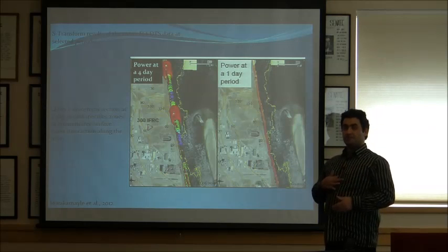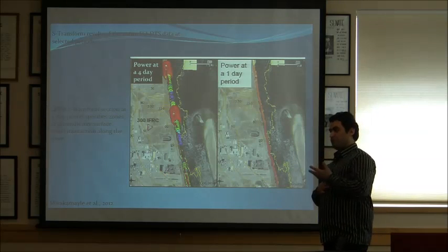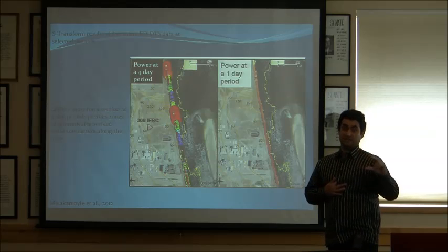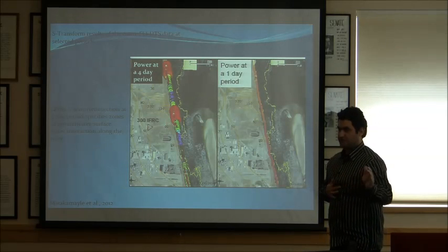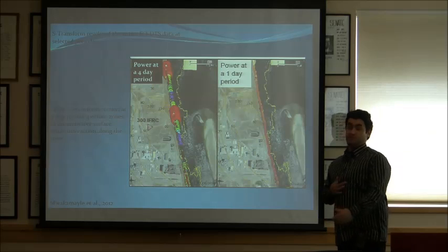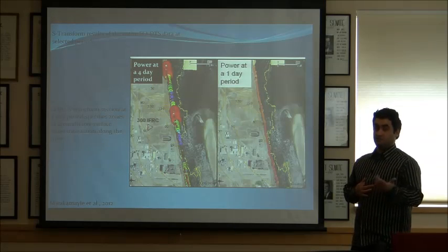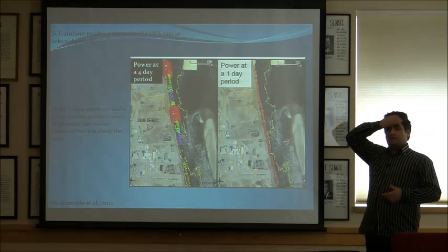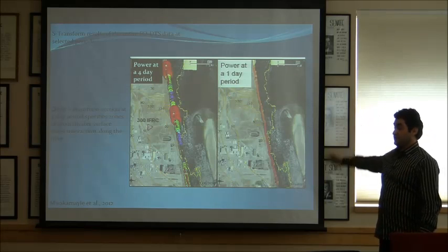And another option, if you're looking for the first 30 meters, say, you can relax your mind, forget about resistivity, and use frequency domain electromagnetics, like the GEM2, that we will have, I believe. And again, people have started using that a lot.